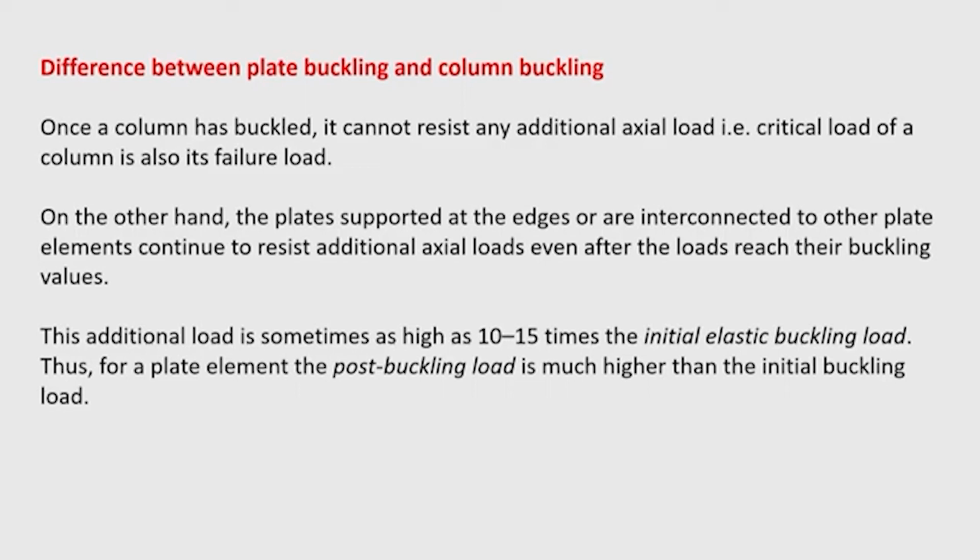So, it may happen that for some support conditions, the number of half waves in x direction is say m, but the number of half waves in y direction may not be m. So, this may be different. So, that we have to find out by detailed analysis. The additional load that plate resists even after the buckling takes place may be 10 to 15 times higher than the initial elastic buckling load. So, for a plate element, post buckling load is much higher than the initial buckling load.